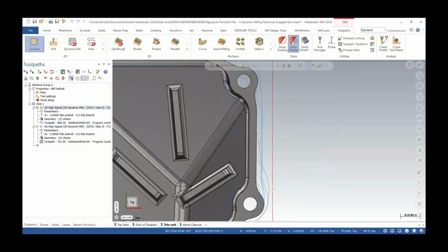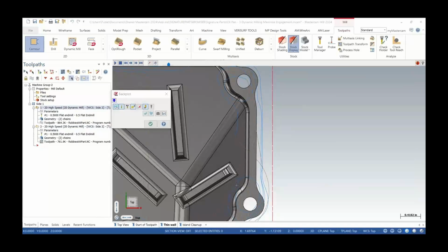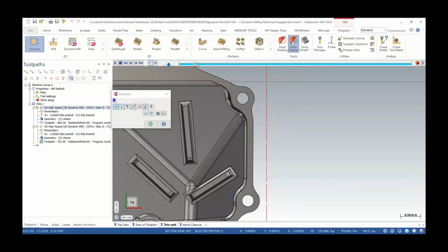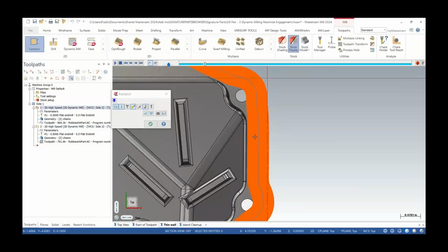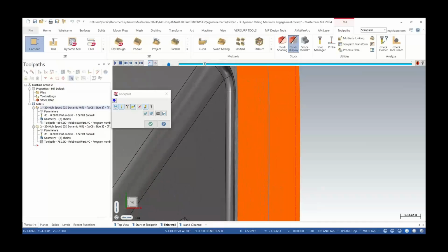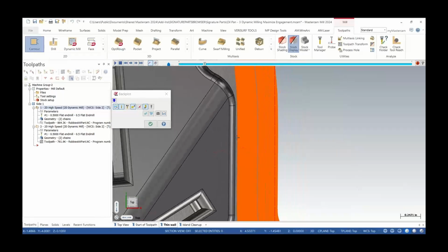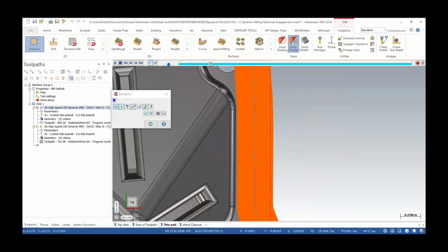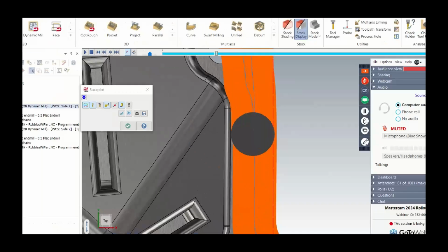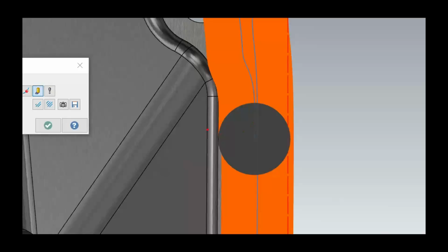So in the first toolpath, we get this first section here with what could perform as maybe a small cusp here. So if I run through the other pass at this, with the maximize engagement turned off, notice that it's not clearing that wall.